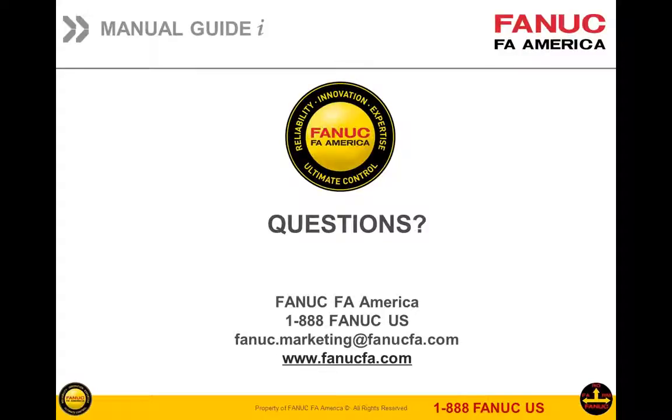Okay. Another question here. With castings, I work above the Z0 quite a bit. How does that work in milling cycles and drilling? Are all Z values absolute, or are some incremental? Well, when we do drilling cycles, it asks you how you want to approach it. There's either initial 1, initial 2, or the R-plane. With the initial 1 and the initial 2, those are incremental values above the part. I think that answers it.